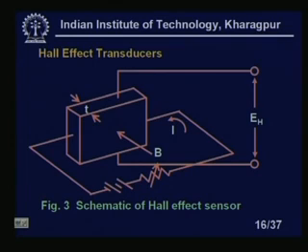I will look at this one, same thing. Okay. I am applying a magnetic field here. A current is flowing through this one. Applying a current, it is coming and it is going out through this. Right. So, Hall potentials. If you take these two terminals, a voltage will be developed. That voltage is called the Hall voltage. Clear again? Right. So, it should be sufficiently thin.